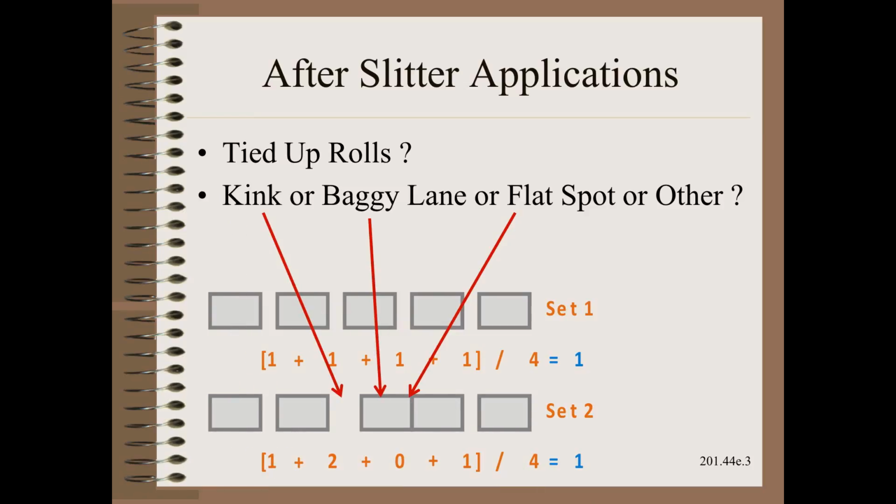The practical concern is that tied up or stuck rolls is common in many industries, especially on two-drum winders or winders with a single shaft. The practical problem is, however, that there are many totally different reasons that rolls could get tied up. This is where knowledge of web handling, plus experience with spreaders, plus clever detective work must all come together.